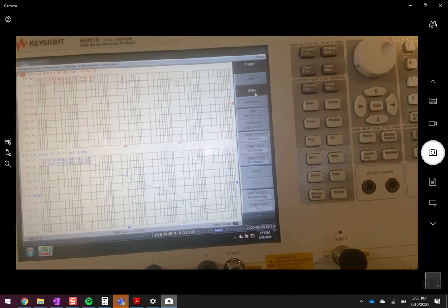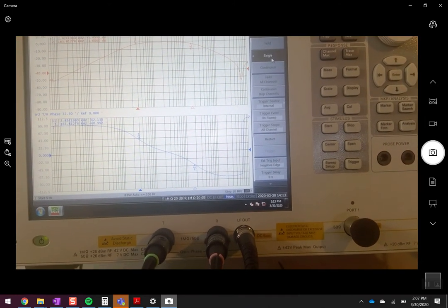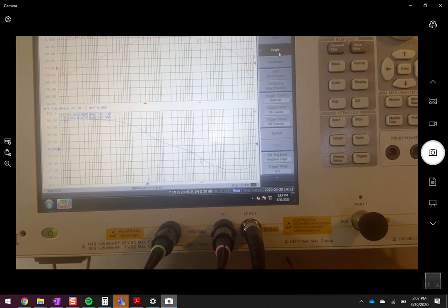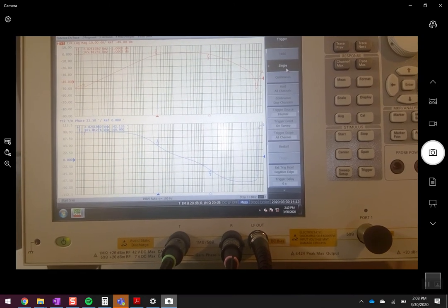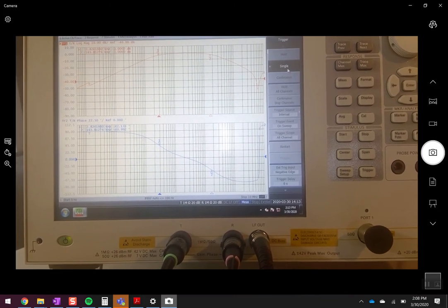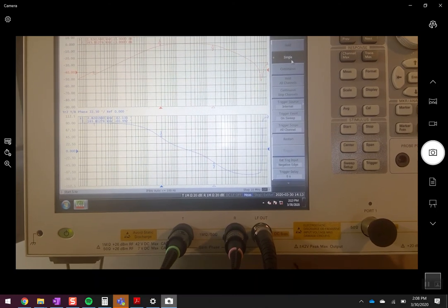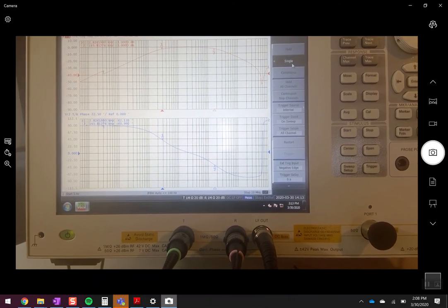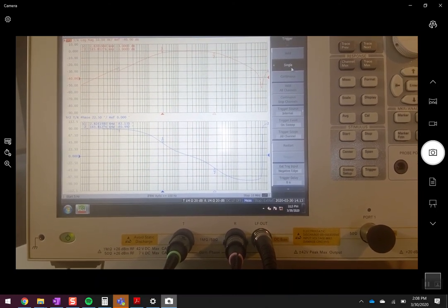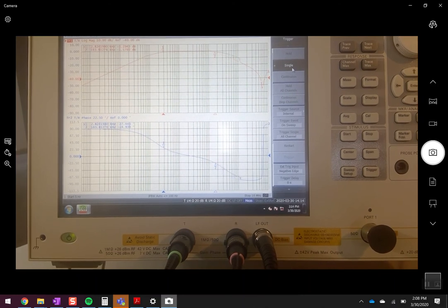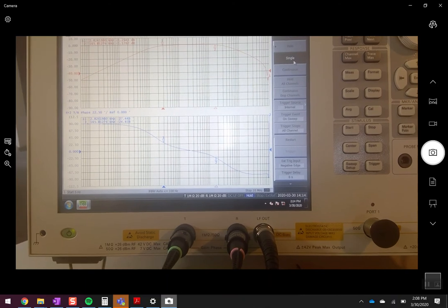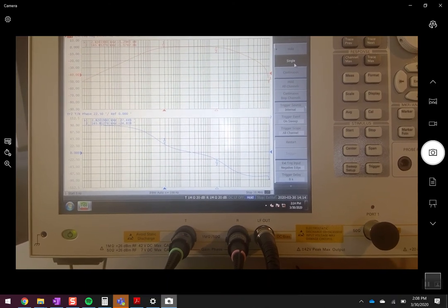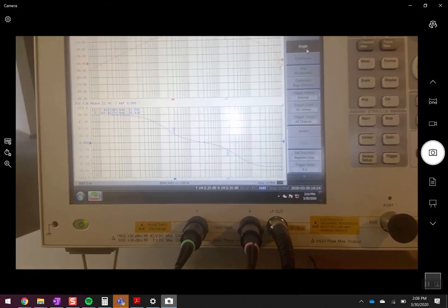See what happens. Well, we can see what's going on here. I changed the other capacitor to make it small, and I changed the first capacitor back to the original setting. So I made that other capacitor, instead of 1 nanofarad, 500 picofarads, or 0.5 nanofarads.